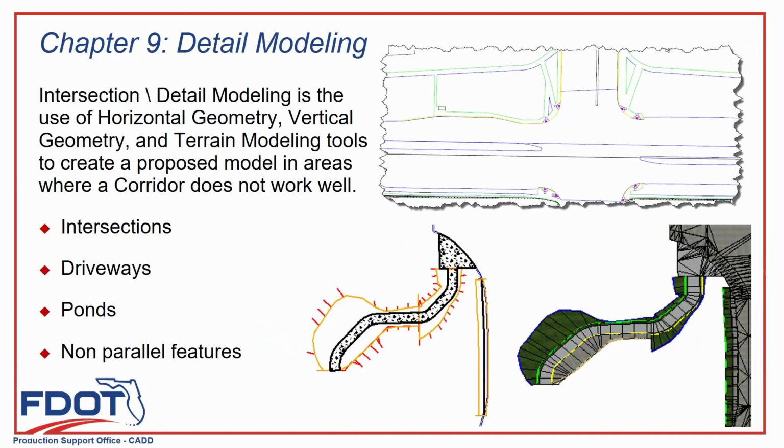So what you do is you model the pavement separately, and then you come in and you have the definition of the median. You just run a curve, just like we could do with that little island. You just run a curve around that, inside to the inside. Once you have the curve, you have the top of curve line, and it's a 3D element in your model. You just select that and say that's a terrain, just like you did with the intersection boundary, where you had to build every little piece. When you do a curve around an inside island, the top point of your back of curve is a 3D line. So you just select that line and say that's a terrain, and there's sod in there, or it's concrete in there.